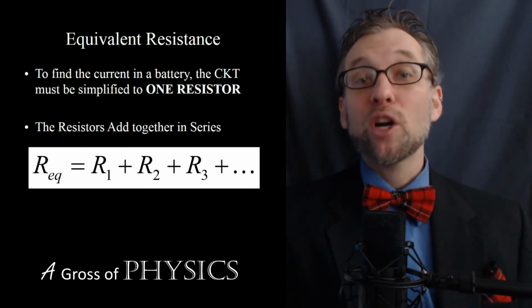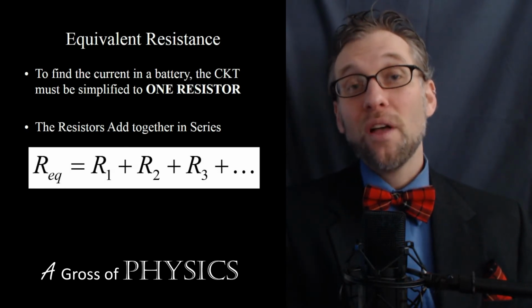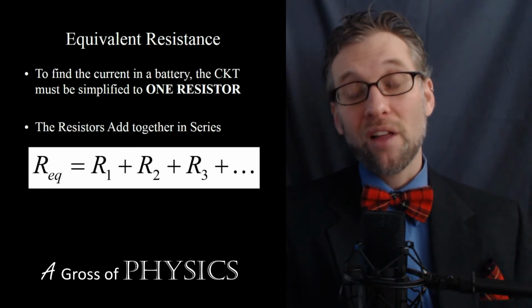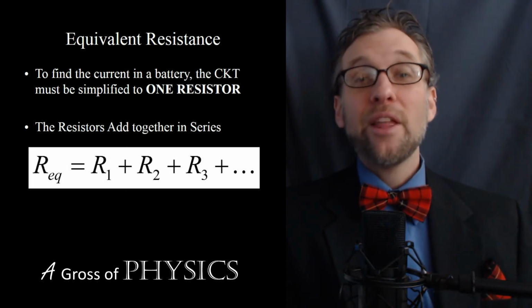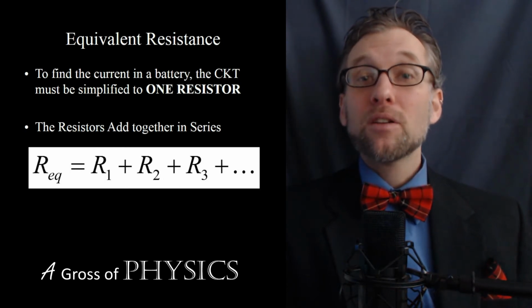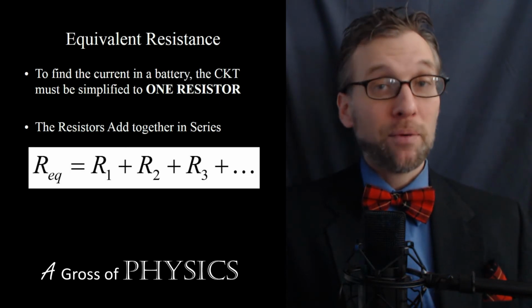Since you already have the equivalent resistance, what the battery sees, that's going to get you the current that is flowing from the battery through the resistors in conjunction with one another. So the way we do that is we add them together, and then we do V equals IR to find the current. Then we can expand the circuit back to its original and analyze each component separately.